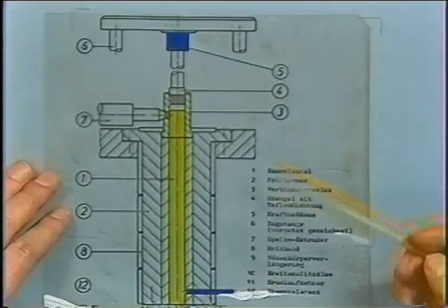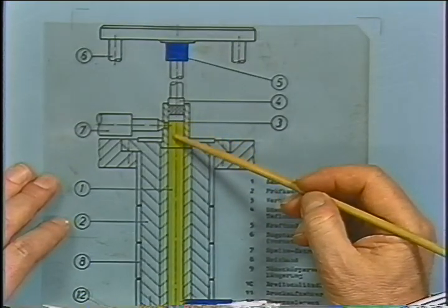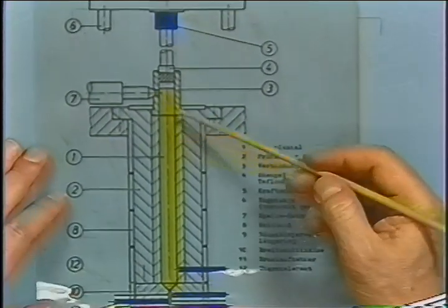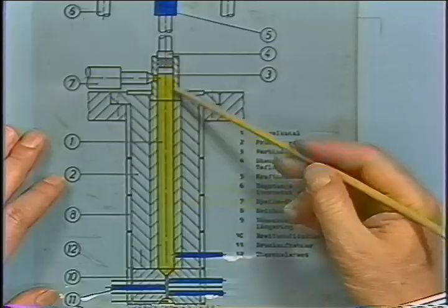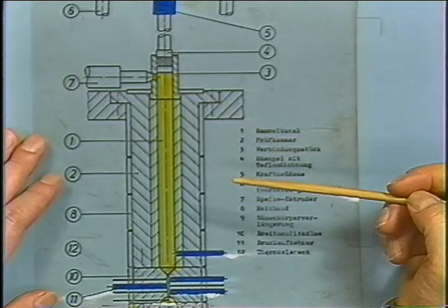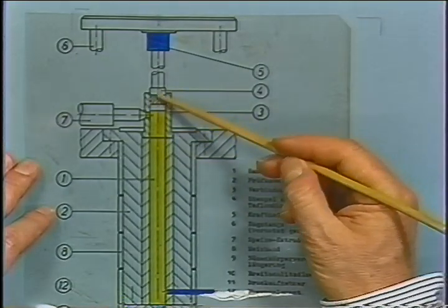The volume flow rate is given by the velocity of this piston times the area of that piston, provided that we reach steady state. When you start up, you first compress this polymer somewhat, but as soon as you reach steady state, this piston velocity gives you the volume flow rate, provided that there's no leak, so we need a good seal up here.